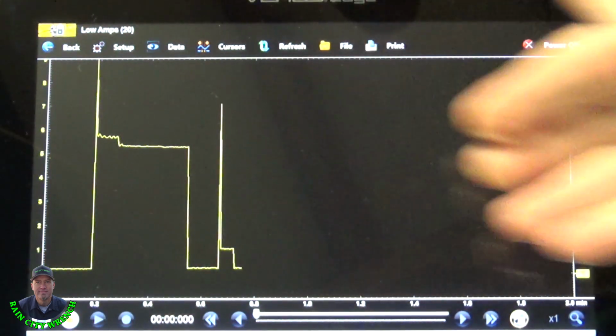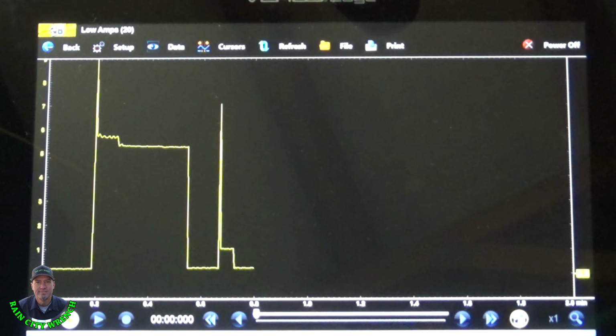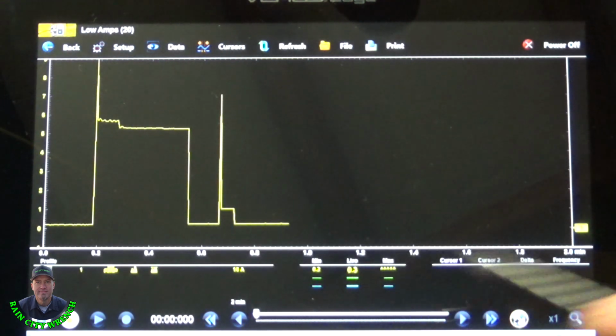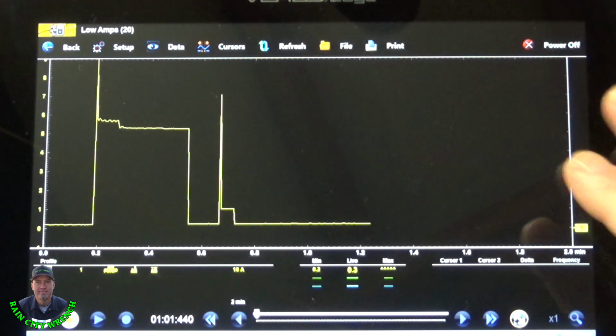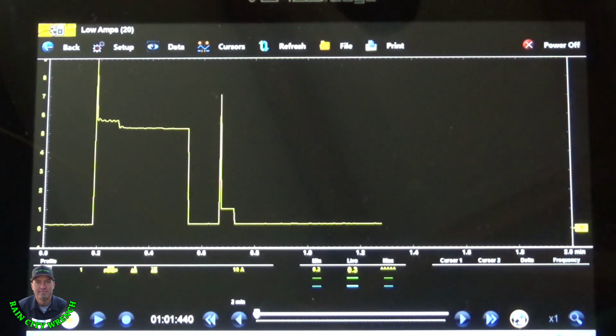Yeah, it's just great to watch them in a graphing mode. So that's what I prefer. We're still drawing that 300 milliamps. Obviously, there's no problem with this vehicle. Now, let's say you got something that's drawing 500 milliamps. You go through your diagnostic procedure at that point. I usually pull up the wiring diagram, a power distribution wiring diagram, and I work my way upstream. Usually it's at an underhood fuse panel, and then I eliminate it to which circuit and go from there.